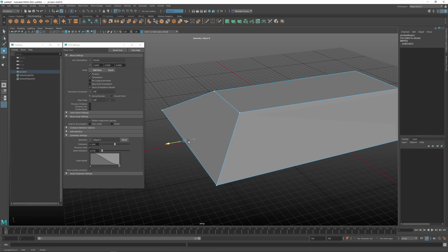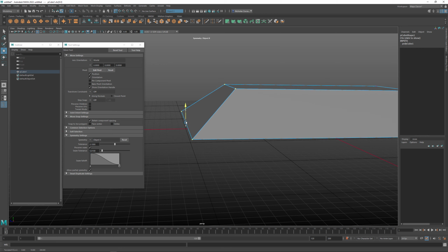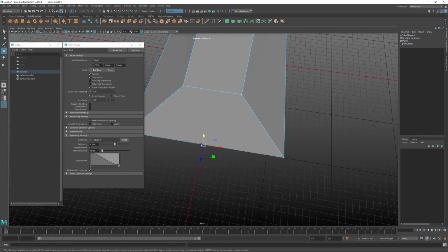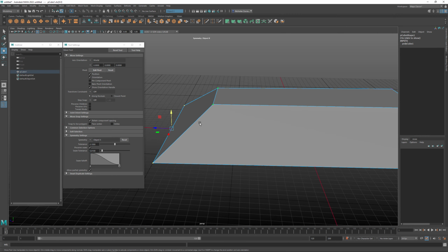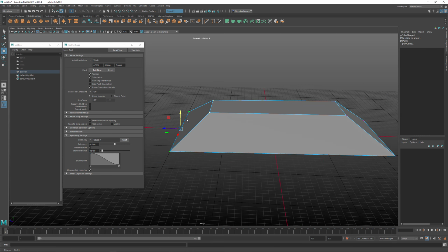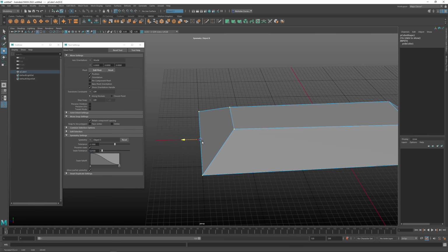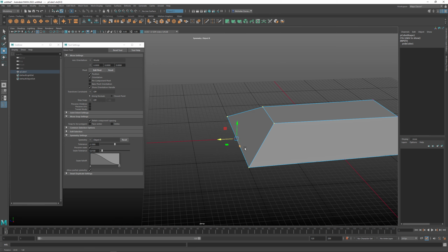So hold down X and I'll click and I'll snap to this here like this, and I'll hold down X and I'll snap, and you can see how now we're snapped completely to the grid here, and these are moving along together as a mass. So now that we're snapped up to the grid, we can hold down X and then move this, and you can see we're moving the whole group and the whole mass of these things together, and we're snapping to the grid the entire time. Okay, so that comes in handy at times.